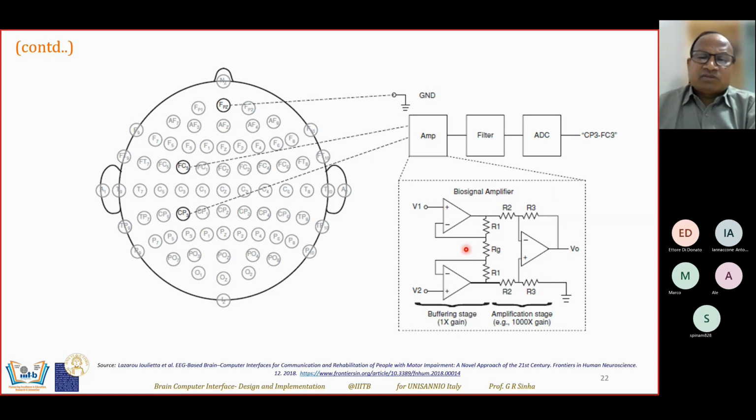So generally what happens, they are passed through two buffers. Right, these are the two buffers where they are passed through. This is also an operational amplifier where there is a direct feedback element and zero resistance in the feedback, that becomes a buffer amplifier. So both the signals directly go here and then you get the inputs and the difference is amplified and you finally get the output voltage here. So gain is very high, maybe 1,000 times or more than 1,000 times.